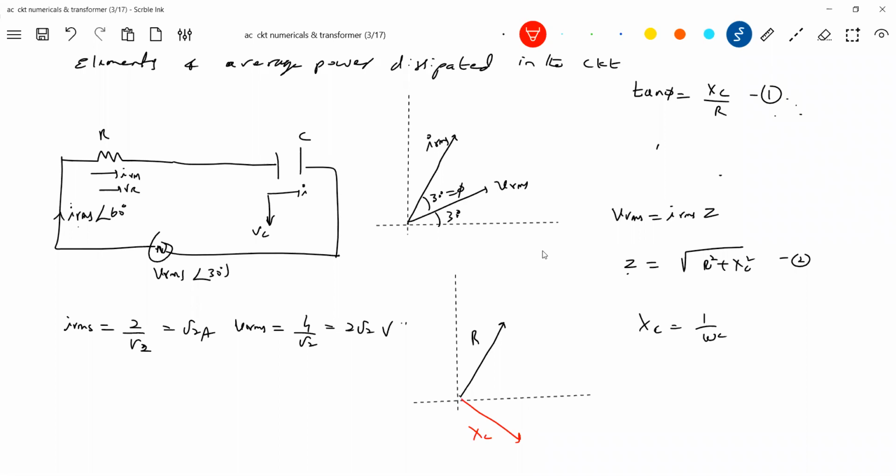Then when you shift this, the impedance will come in this way. And there's a phase angle. It's not always zero phase. Here, the current is having phase angle 60 degree and the applied voltage is 30 degrees. The triangle. So sometimes they may give this phasor diagram like this. From here, you are supposed to work out.